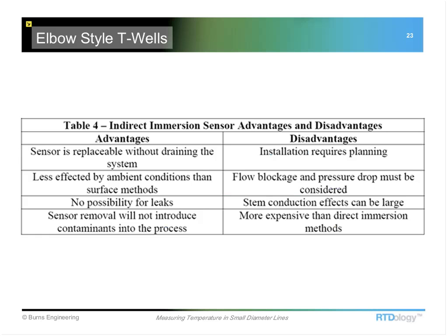So again, the advantages with adding a thermal well like this: we can replace that sensor. We can calibrate the sensor, pull it out. We don't have to drain the system. It stays enclosed. And for a lot of things, that's going to be a huge advantage.